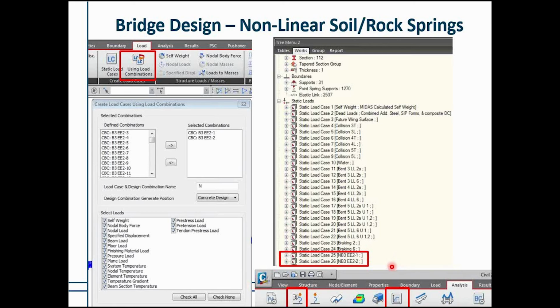As we were doing this, I talked about how we had to have at least 4 models to model our substructure as far as different load cases and scour effects. But when it came to this process, we realized that the file sizes grew very large very quickly for each load combination that we were turning into load cases. So we did have to have multiple models because we would exceed the file size, which wasn't a problem. We just hoped to only have 4 models, but because our geometry is so large and we had so many forces, we were reaching file size limits, and we had to go to multiple models for certain design cases.